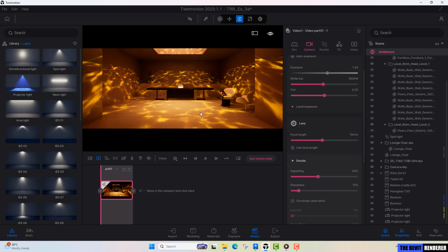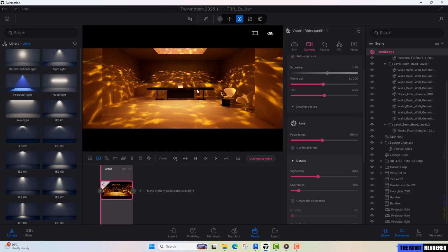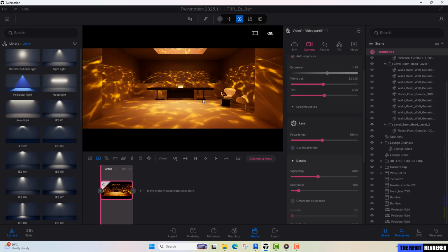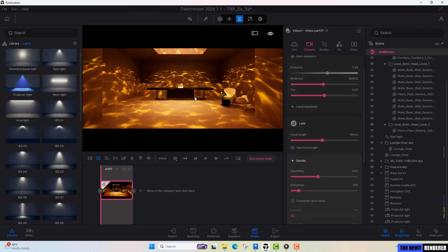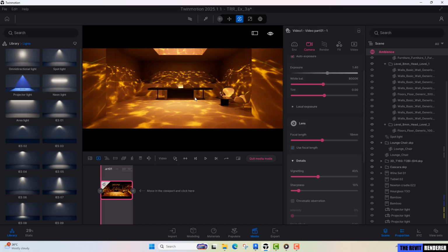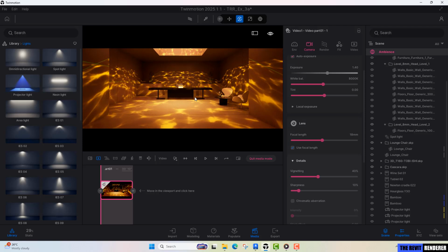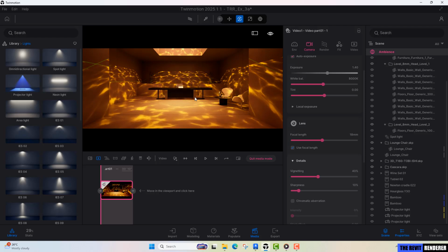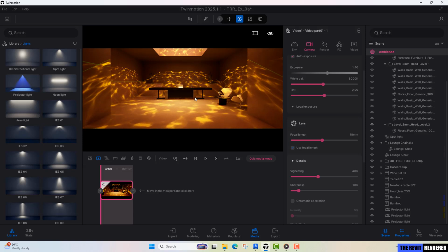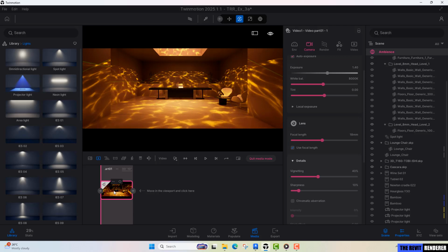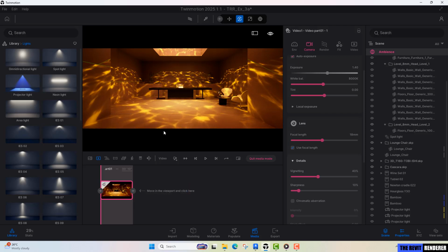So I want the video to end a bit more zoomed in, but I want it to start a bit more zoomed out. So I'm just gonna press the S key on the keyboard to go back a bit, and here you can use camera speeds of maybe 1 or 2 only, so that you're not moving too fast. I'm just gonna move it back until you don't see that clipping happening. Then I'm gonna refresh this first keyframe to capture that small change.